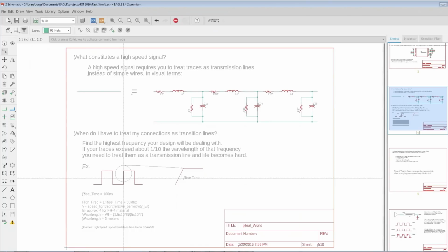For most of us who've worked with electronics for any amount of time, it should be very familiar. It's basically the relationship between voltage and current. It's the ratio of voltage to current. In a resistor, it's a steady value. It's very simple. It's basically always whatever the resistor value is. But now when you're dealing with inductors and capacitors, you have a frequency-dependent impedance, okay? So impedance is more general than resistance. You can always talk about impedance. You can't always talk about resistance, okay? So that is the key term, and you're going to see it pop up a lot.